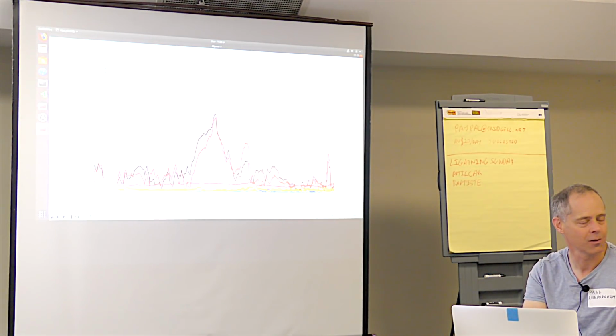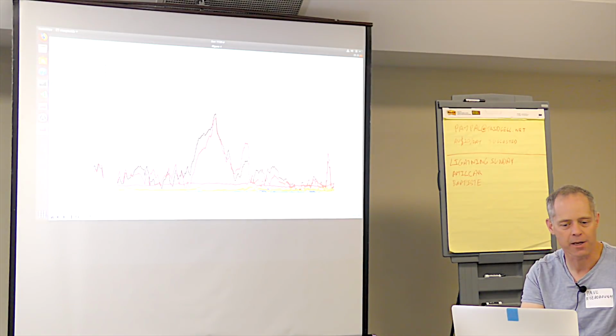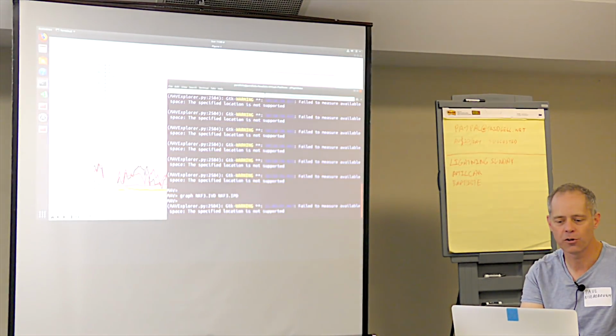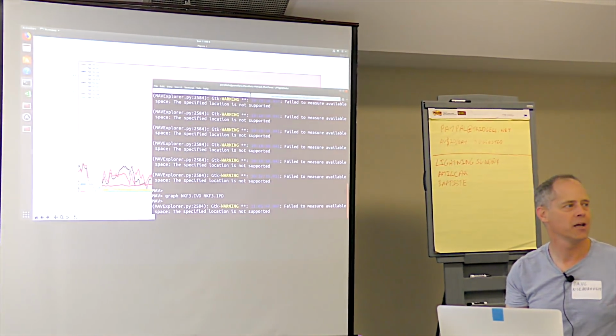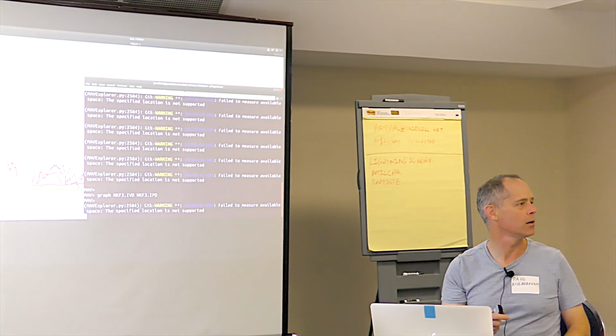Well, that's of interest. Now, that normally doesn't happen. That could be two causes. It could be a glitch on the GPS. So when we have a look at a glitch, the best way to tell if you've got a velocity error on your GPS is to have a look at the vertical velocity of the GPS.